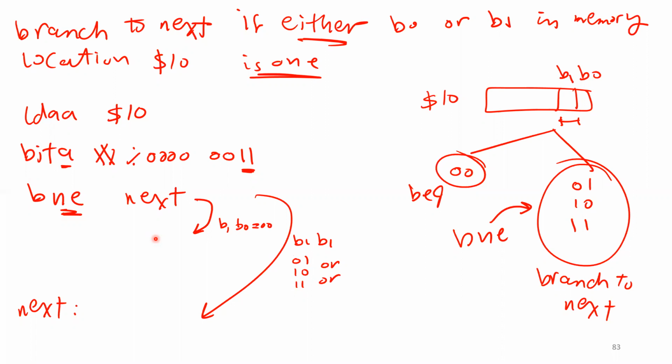The other thing is, if you have a byte, how can you manipulate some bits in this byte and not change the other bits? Manipulate here means, how can you set, how can you clear, how can you flip some bits? And we are going to need it next chapter again. Okay, guys? It is very important, that's what we are going to need. We use it a lot.